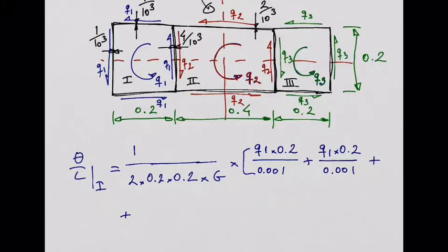So in that wall, there are 2 shear flows there. We have Q1 going upwards, and then we have Q2 going downwards. So what we need to have in that wall is the balance or the summation of these 2 shear flows. So what I will have in this wall is going to be Q1 minus Q2.